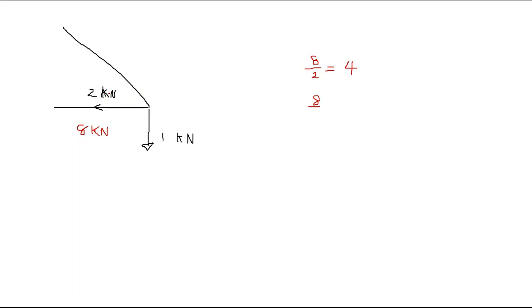So when you increase the force here, let's say the ratio between these is 1/2. If this is 1.5, this will be 3 kilonewton, so your factor of safety is reduced to 2 point something. Likewise, you can increase this until it reaches 8. If it reaches 8, the factor of safety is exactly 1.